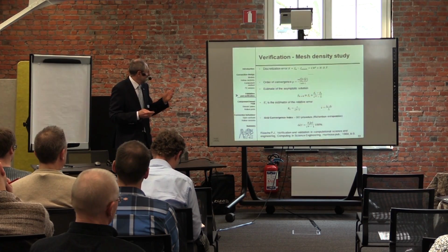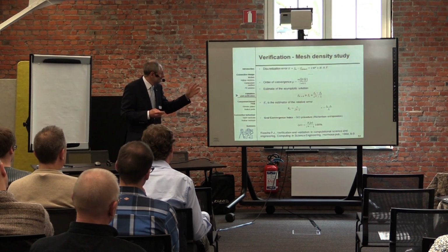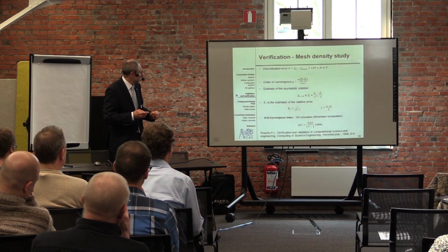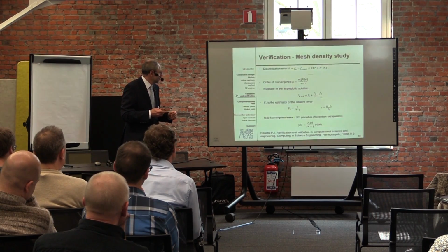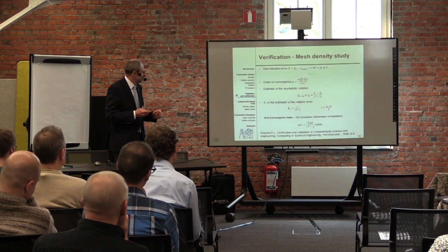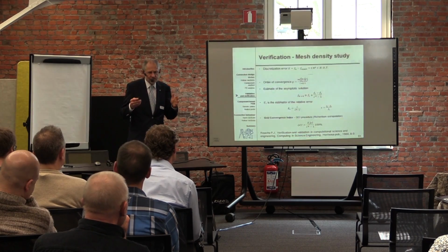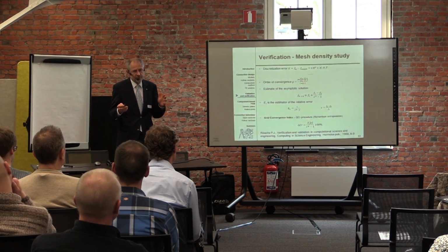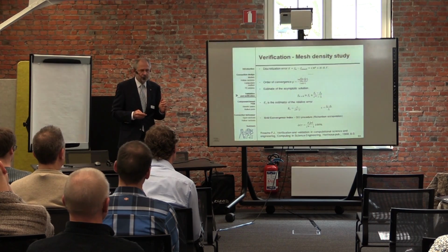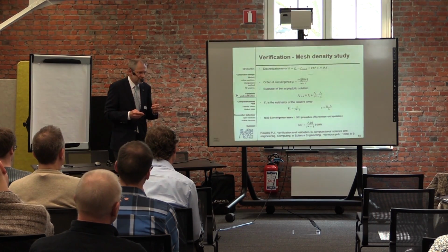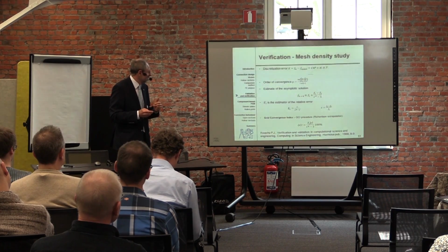So these are, let's say, 2 very simplified versions of these thick books and very nice papers, very nice work. I have here this assumption solution, so it's not linear, it's Richardson extrapolation, called the grid convergence index, that you calculate based on the three assumptions. You calculate your grid size. So this is the most popular and the most acceptable solution to reach some accuracy.